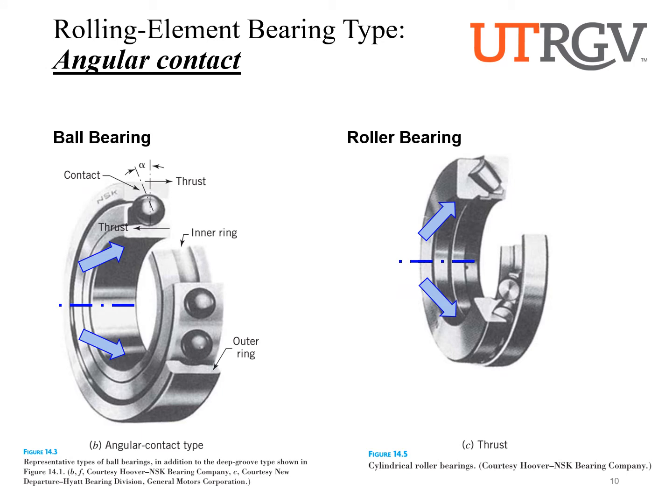We also have angular contact bearings. These are going to be in between the two. So these are bearings that can take a radial load, but some thrust load at the same time. How do we do it? Well, look at how this guy is machined. The picture's not very clear, but maybe we can see it better with the roller bearing over here. See how those bearings are, for one, tapered, and two, at an angle. They're not horizontal or vertical, but at an angle. These types of bearings, again, are going to take radial loads and thrust loads.